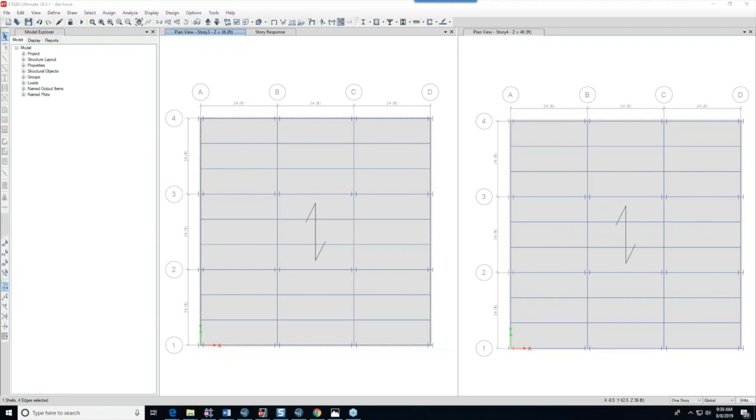Now, there are cases, let's say, where you have girders or beams that are spanning in one direction, maybe floor joists marching along at 4 feet on center, and they span 40 feet. Well, do you want to model each of the joists, or for your seismic model, you might choose to eliminate each of the individual elements and just come up with an equivalent deck? The load path is still the same. You're still accounting for the proper gravity load path to the columns, but you've eliminated a lot of detail.